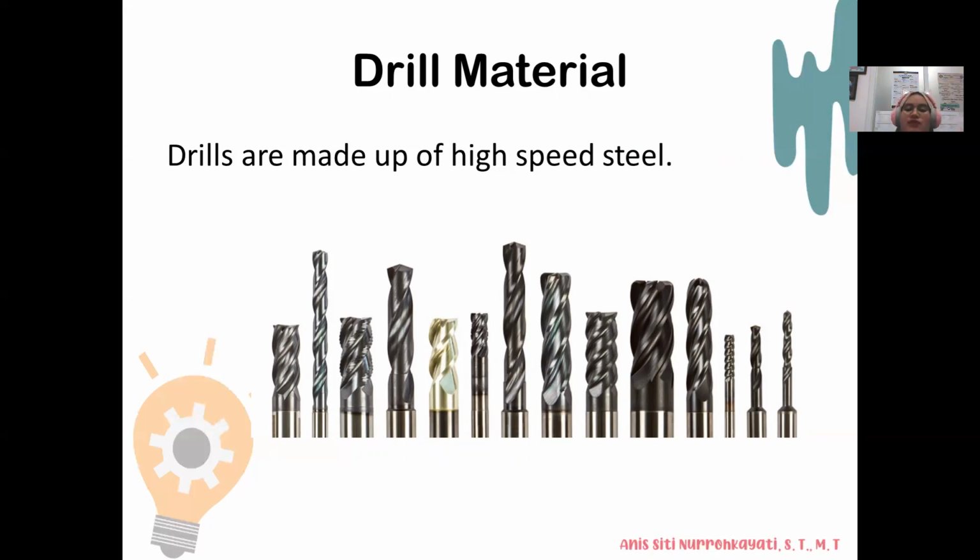So if our workpiece is more difficult to cut, we can use HSS alloys of the high cobalt series. This is an example of a drill.